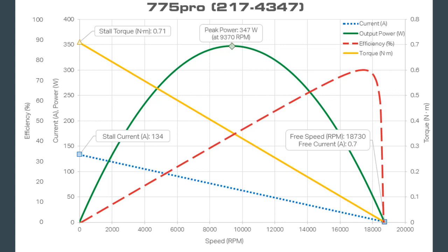The main breaker will pop, but it doesn't automatically pop back. A human has to physically come in and pop it back. So if you go above 120 amps for too long and you pop your main breaker, which 254 has done on multiple occasions. In 2014 they had problems with Aerial Assist, their world championship robot. I think part of it was such a pushing game, so I think that had an impact.